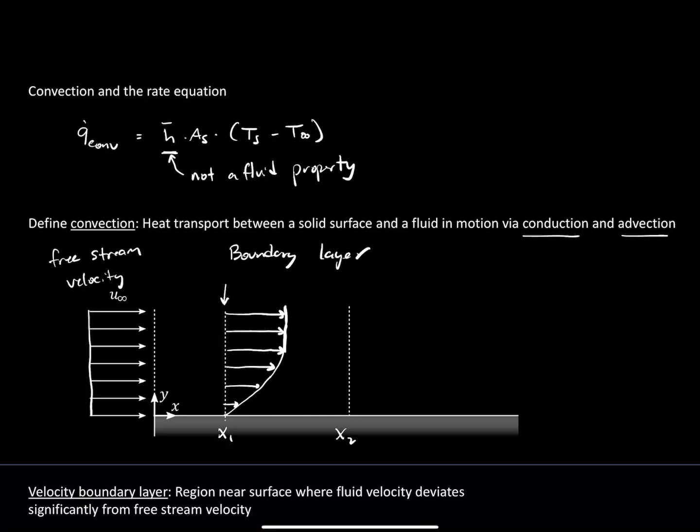If we go even further, at x2, now we sketch the velocity profile out here, we note that there's been more room for this shear stress to propagate through the fluid. So maybe very far out, you still have the velocity profile unaffected. But as you start getting closer, you're going to notice that the velocity profile has been affected. If we sketch that, it looks maybe something like this, where out at this position, those are the positions where we can say that the velocity hasn't been affected.